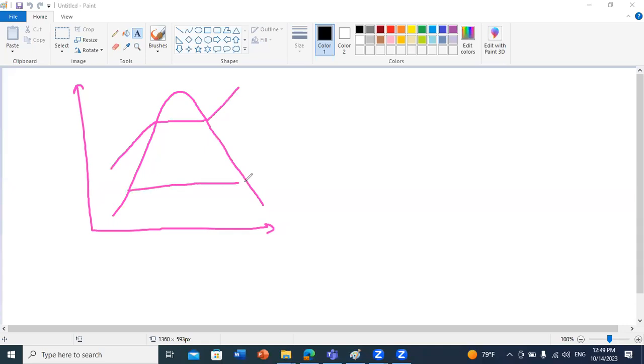As we mentioned before, in the case of power cycles, it's advised to have as high a quality as possible at the exit of the turbine, because this will first enhance the efficiency of the system. In addition, it will reduce damage to the turbine. We can do a similar analysis here.